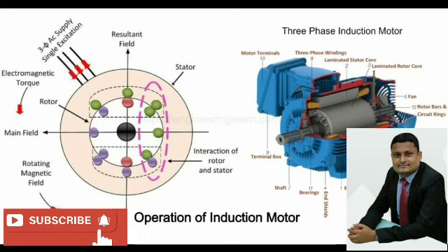Now the last thing I am going to discuss, the number of stator slots. The number of slots per pole per phase should be a multiple of 3 for integral slot winding. Let us take the value q as 3. Total number of slots Sg is 3 into 4 into 3, that is 36. The stator slot pitch, tau_Sg equals pi D by Sg, pi into 0.1175 divided by 36, will come 10.25 mm. The guideline was a slot pitch between 15 to 25 mm, but for smaller machines it can be lower than 15 mm also.